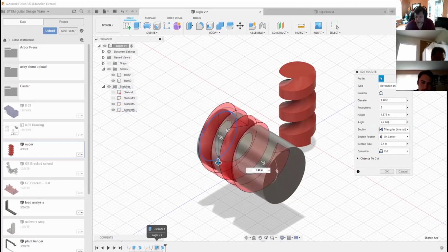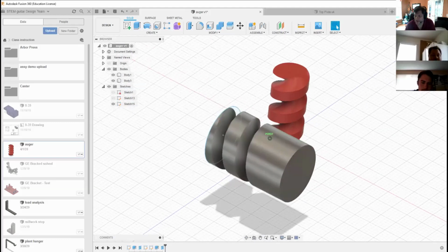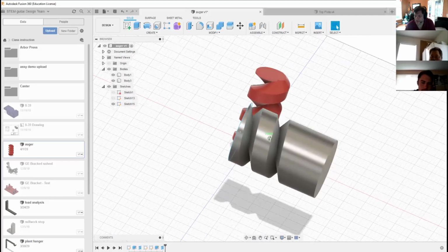If you notice what I was working on in here on the bottom, I dragged the cylinder before the other coil. So I just dragged it into the orientation that I needed. And now with this coil, I'm going to change it from creating a separate new body into a cut situation. And now it cuts that coil. Makes sense?